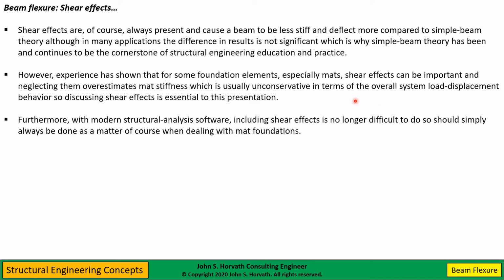Certainly now with computer software, including shear effects in analysis is not a problem as it was in the past. And really, in my opinion, it should be done as a matter of course when dealing with mat foundations.